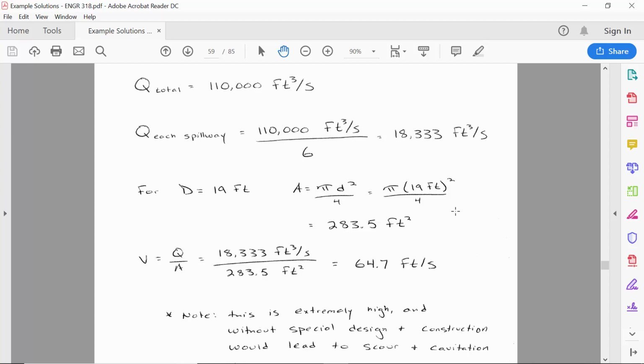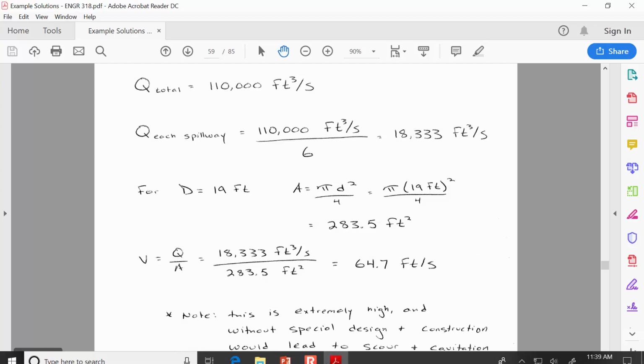So what can happen in a situation like this is that the water's moving really fast, but then there could be these little bubbles forming. And bubbles aren't great because now you've got something that's going to scour the concrete even more, those gas bubbles, especially when they collapse. Eventually those gas bubbles will go through some section where the pressure is a little bit higher, and so they will collapse and send a really high pressure shock wave through the water that can pit the concrete that this material is made out of. And so there have been instances where pipes have failed for this very phenomenon.